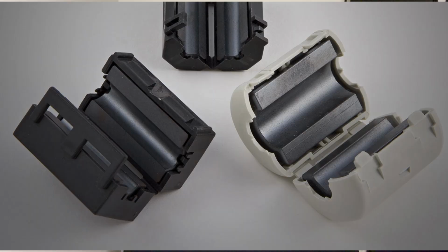Another component you can add to your cable assembly is what's known as a snap-on ferrite. These are probably something that you've seen all around in the world of electronics, where you have a power supply that has this weird cylinder attached to the cable and you're not really sure what it's for. And the answer is it helps reduce your common mode emissions. These ferrites are very easy to use, and you can just literally snap them onto your cable assembly and immediately see if they impact your EMI.